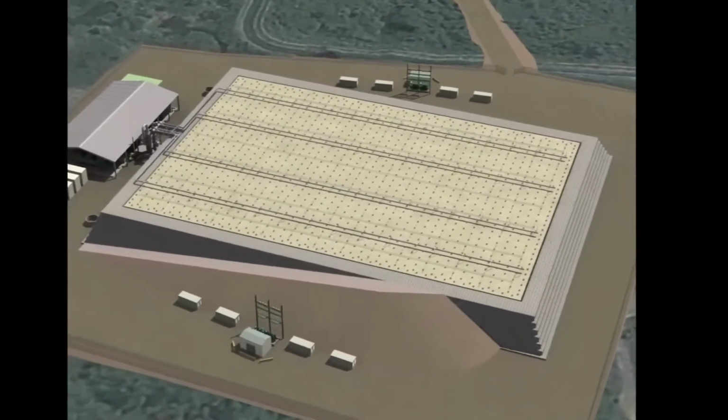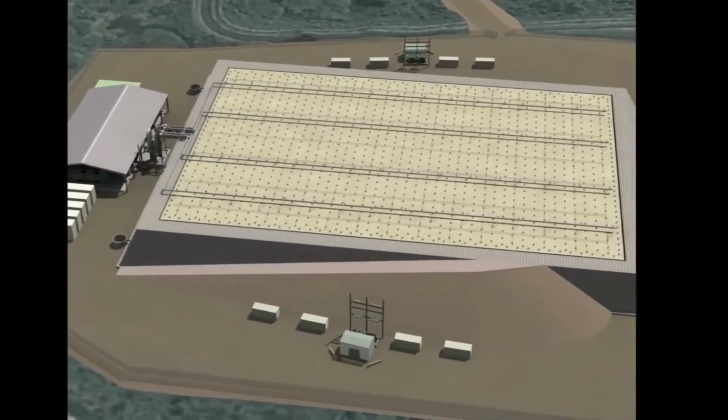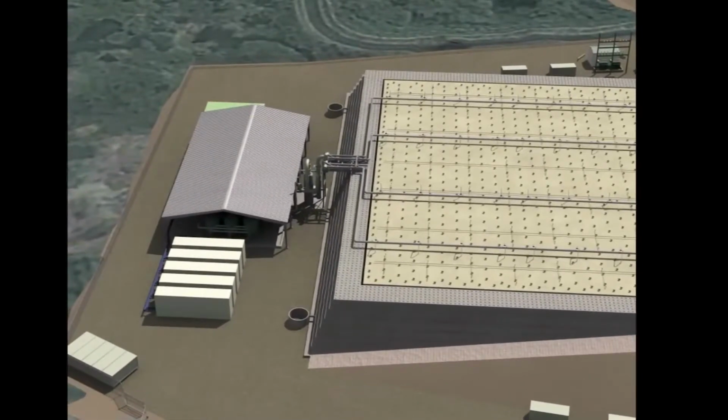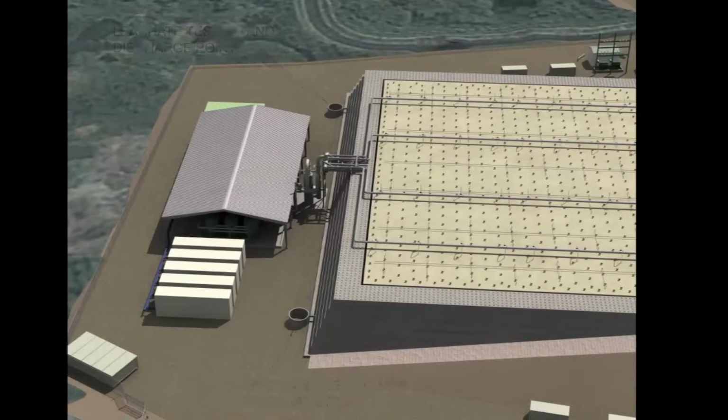Once the IPTD system is started during each treatment phase, it will gradually heat the soil and sediment to a target treatment temperature of 335 degrees Celsius or 635 degrees Fahrenheit. This will take approximately 4 months for Phase 1 and 6 months for Phase 2. The prolonged exposure to high temperatures causes the dioxin compounds in the soil and sediment to break down into non-hazardous byproducts such as water and carbon dioxide.